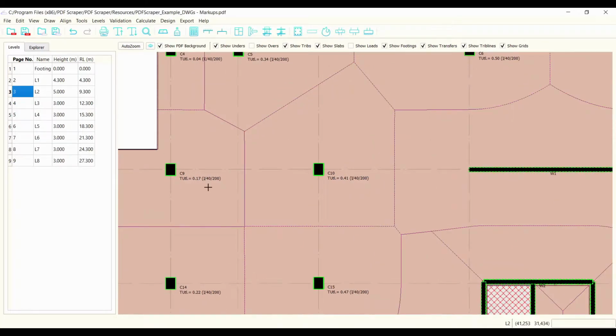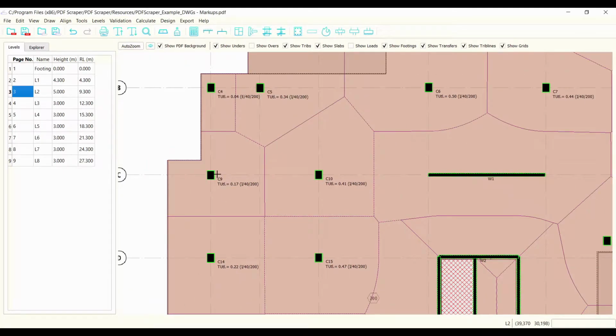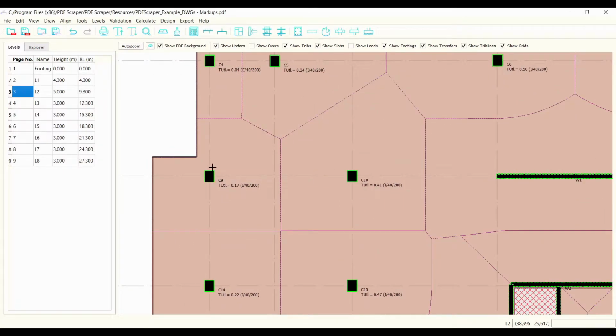So there's 3 parts to this code. The first one is, in this case, an I. That is the confinement condition of the slab concrete. The second one is the assumed grade of the slab concrete, and the third is the assumed thickness of the slab within this check. Where you've got complicated slab geometries and potentially slabs with different concrete grades in the same region, it's just useful to validate that these design values are appropriate for the situation. The algorithm used to do the transition check is relatively simple, so it's just a matter of validating that these values are appropriate.